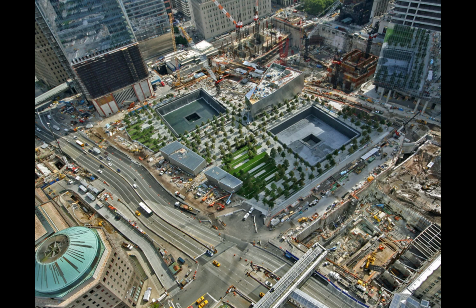And again, once you're above ground, it's a little easier to feed all your buildings. Your tower cranes are basically self-supporting. They get to do everything they need within their footprint of the building, and you're not doing as much coordination with all of the other activities. So once this central area got opened up, it was a lot easier for each of the buildings to get their own equipment and materials into wherever they needed to.